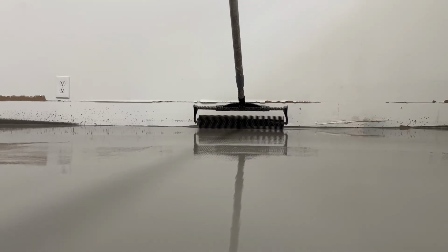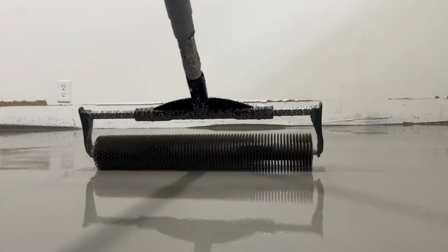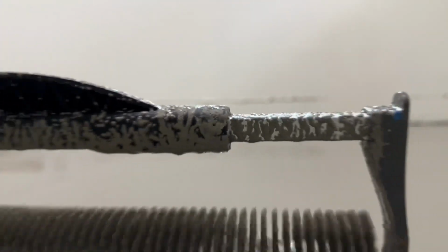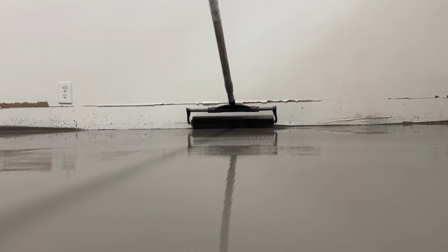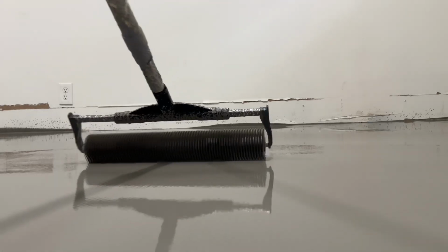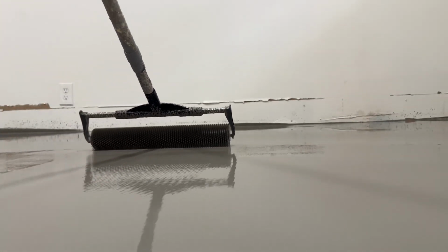Then you want to wait for the right environmental condition. Here in Florida, it is blazing hot during the day year-round. So we want to lay our coatings either really early in the morning or more towards the evening time. If possible, you want to shield the concrete surface from direct sunlight during coating application.